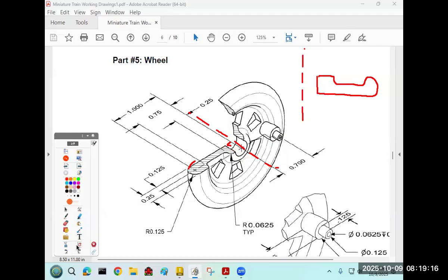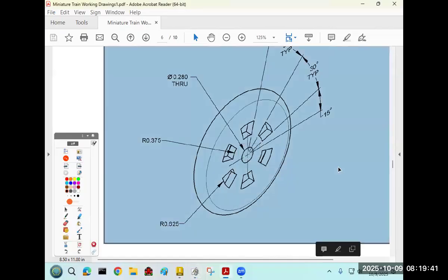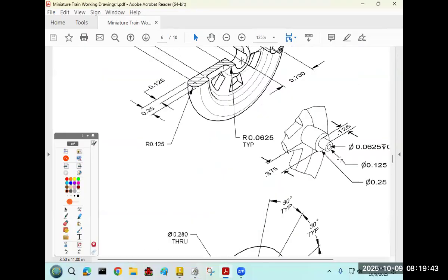We are going to pretend like it's solid there for the sake of our sketch, and make this as if it was there. And then later we will cut the hole once there's something there. We'll draw a circle and cut the hole there afterwards. Okay, if that felt like a lot, it is.